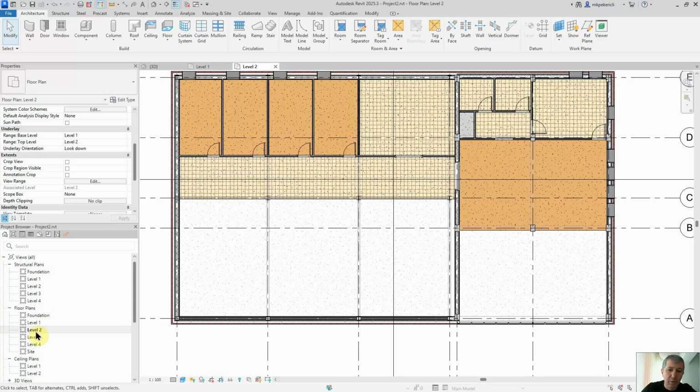Right, so the first stairs that I would like to put is in this area. Now this is the first level, first floor, which is defined as level 2, as we are using the American standards here. Now we'll start at the ground floor like that, then we'll turn around and go up. Okay, so that's what I would like to do. Because I would like to make an entrance from the side, on this side, and then we can have a lobby area here, and then maybe some back office on the first level.